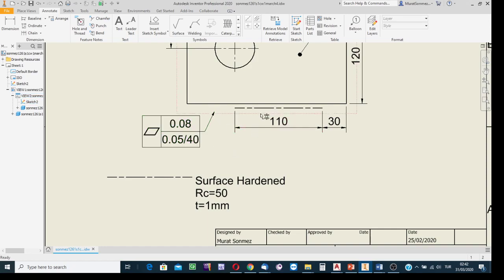Otherwise, when I delete the chain line, this annotation, since it is connected to the chain line, will also be deleted. Then, to demonstrate how a chain line is created in Inventor, delete the already created one. I select it with a click and push the delete button, and also delete this footnote marker and recreate it.